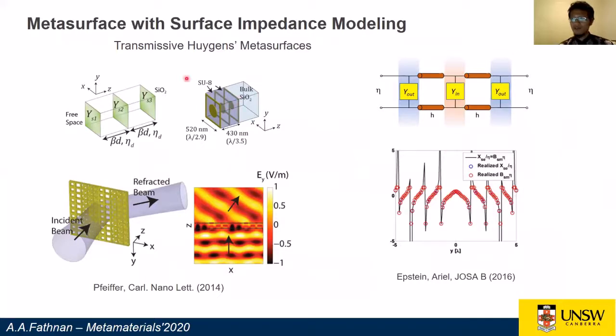To achieve high-efficiency transmission operation without changing the incident polarization, we can use Huygens metasurfaces. Using this approach, full control over the transmitted beam can be realized by conditioning the meta-atom to exhibit strong magnetic response in addition to electric response. For wavefront manipulation, the concept here is to excite properly phase-shifted electric and magnetic dipoles in equal amplitudes, such that high-transmission copolarized operation can be obtained while tuning the phase over 2π.